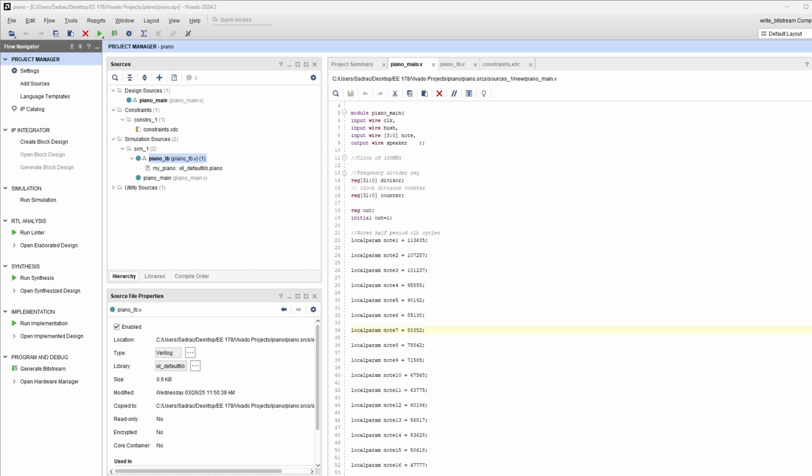is that we know we're going to want a clock, right? Because from the clock that's coming from our FPGA board, which is 100 megahertz, we're going to be using that clock and manipulating it so that whatever frequency we wish to utilize, we can just grab it and implement it, right? And we'll be using this process by essentially doing a counter, and I'll go step by step on how we're going to be quote unquote grabbing such frequencies.